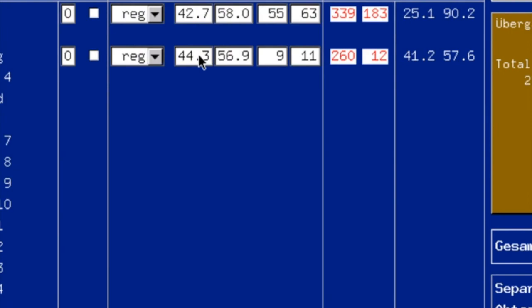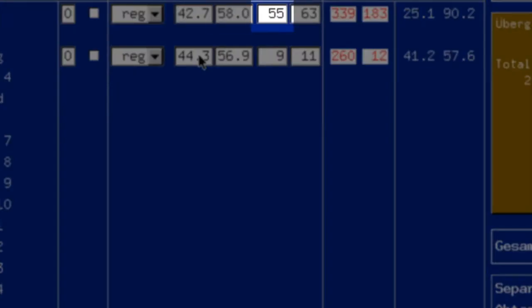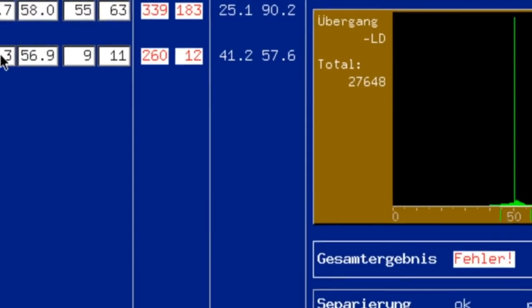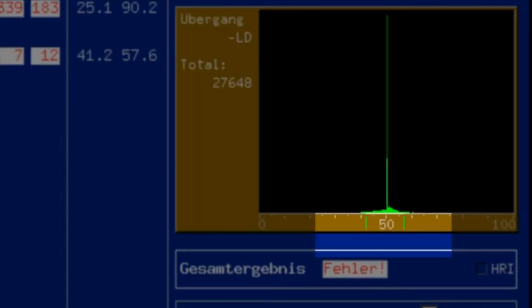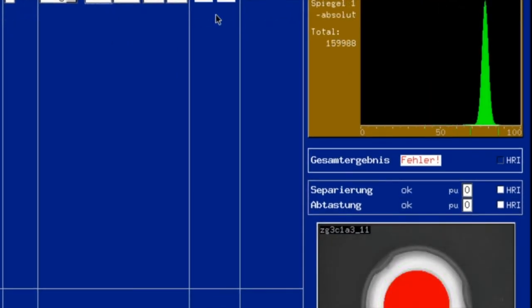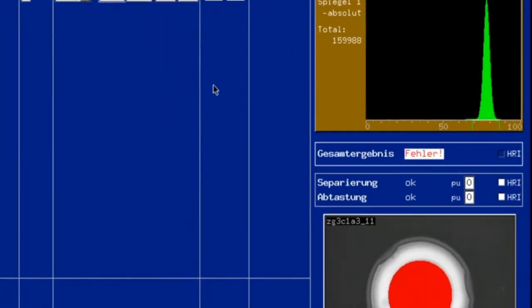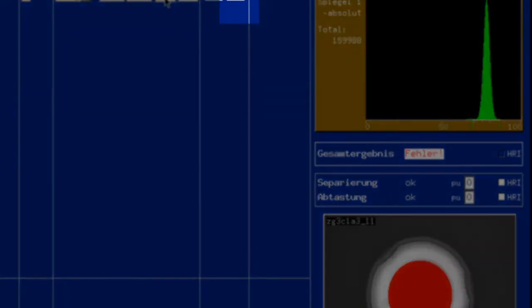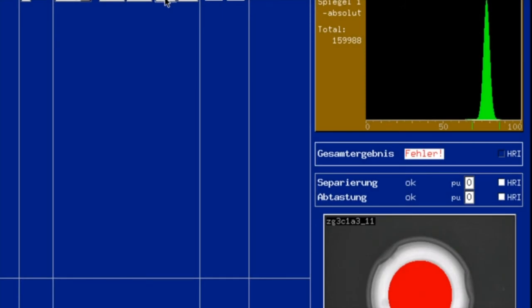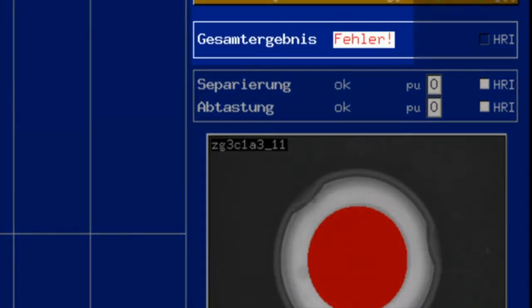In regular mode, there are parameters like min, max, low and high. Min represents the higher and max the lower threshold value. The parameters high and low form the tolerance values in pixels to the left of the lower threshold and to the right of the higher threshold. High would be the amount of the brighter pixels outside the defined thresholds. If the amount of pixels overruns the threshold value, the area will be displayed red and the product will be classified as faulty.